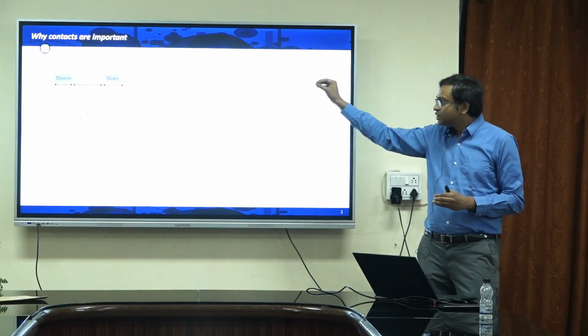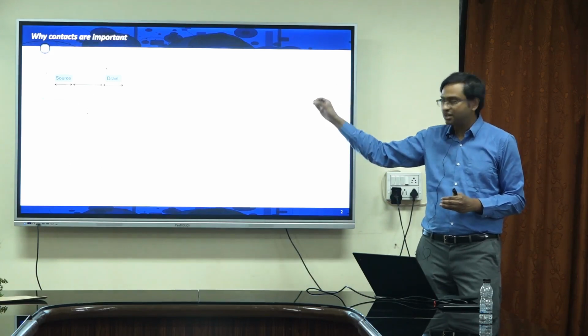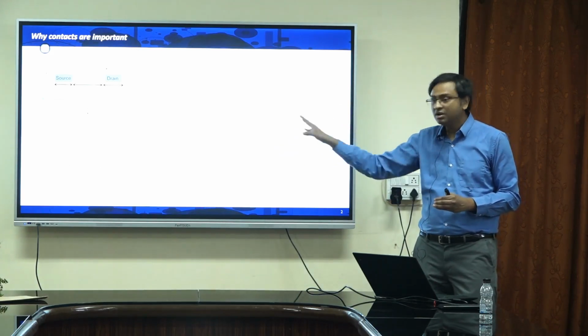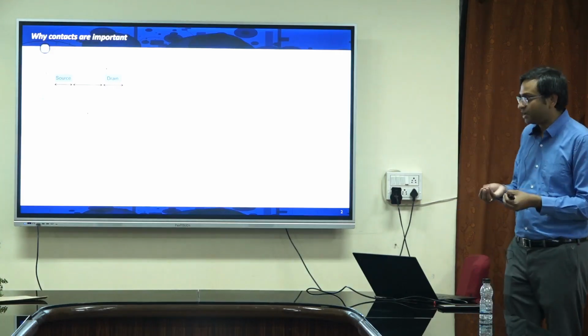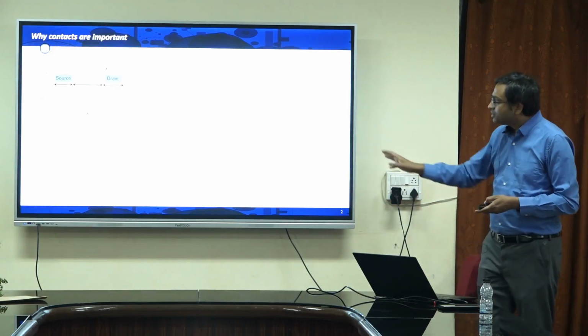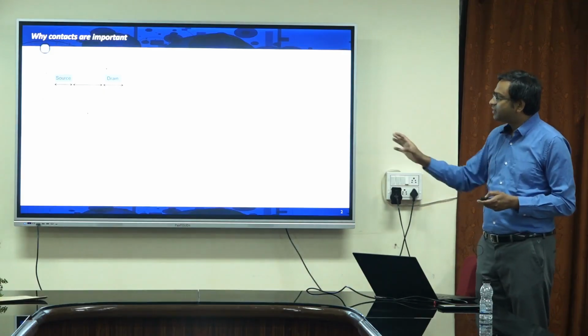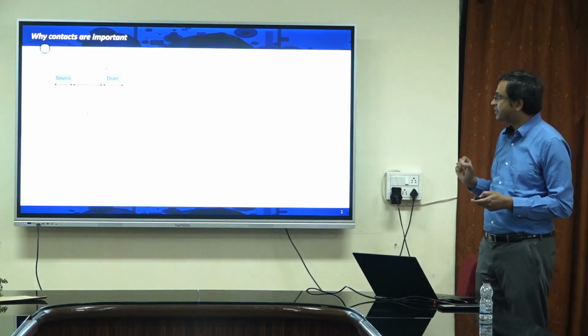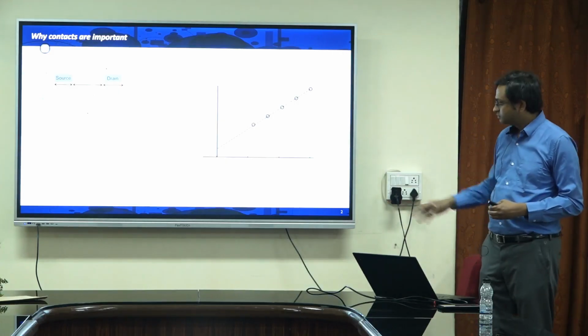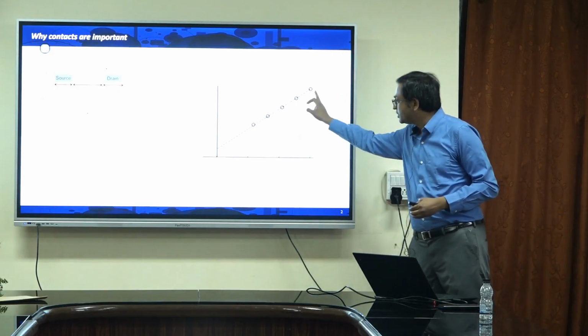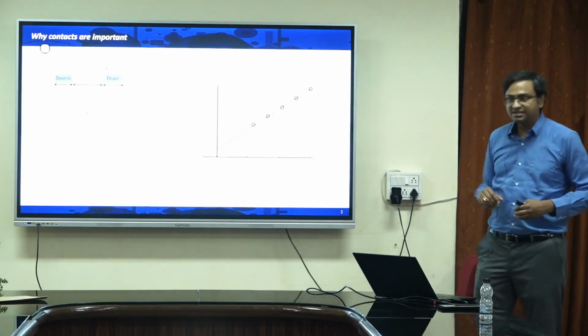So if you use 2D material versus silicon versus germanium, what is going to change is your RSH, because that is the fundamental material property, and the rest is design. So this is the channel resistance. Now if I wanted to plot the channel resistance as a function of the channel length, then I will get this linear line. You can see over here, as the channel length becomes smaller, the RCH becomes smaller,